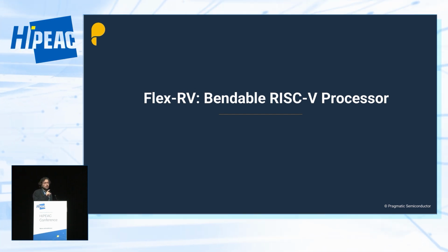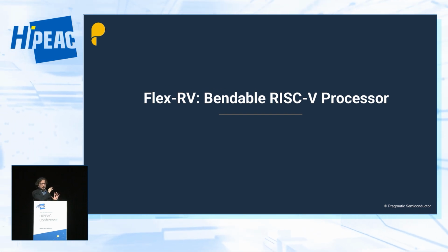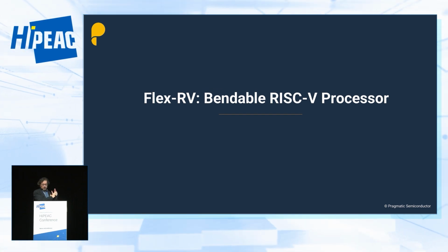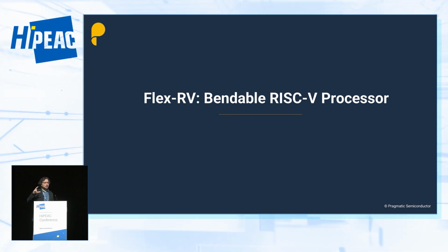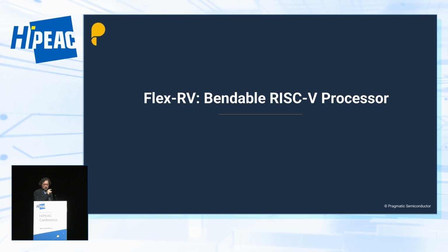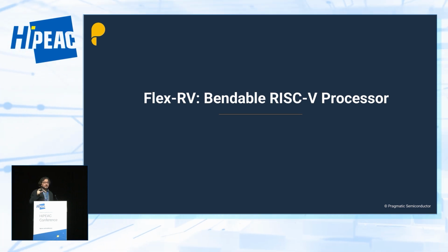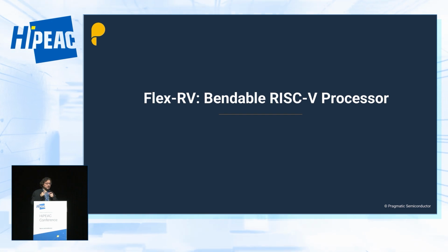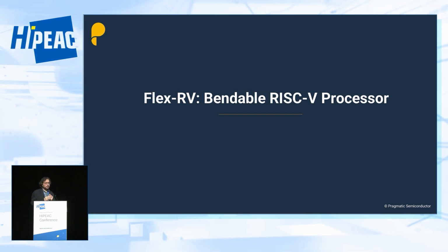I'd like to say one more thing here. So far, the prototypes I showed you, the domain-specific and general purpose ones, were fabricated but tested on wafer. With the plastic arm, I think we diced it and integrated it on a rigid PCB, just as a proof of concept demonstrator.